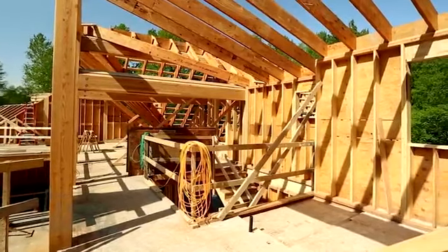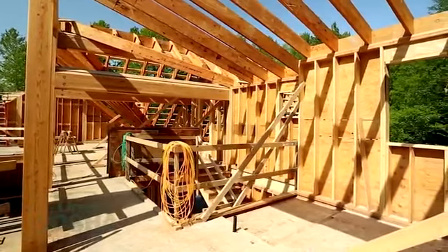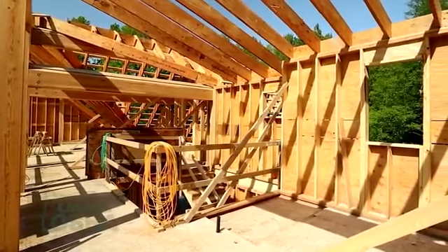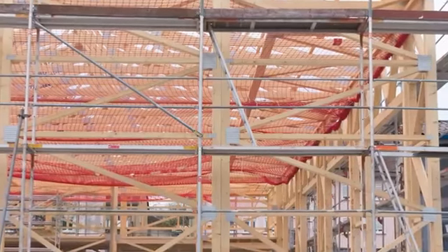instead of trying to tie people off and keep them from falling towards the interior? Because we use a lot of guardrails once we're framed up on the exterior walls to create protection on an exterior fall, but we still have falls a lot of times to the interior of the building. Are there ways to fill that void with something so that we don't have a 6-foot fall, or if somebody falls, they fall into or onto something like netting for the interior? So we need to start thinking out of the box when it comes to framing and wood framing especially, on what our fall protection solutions could be.